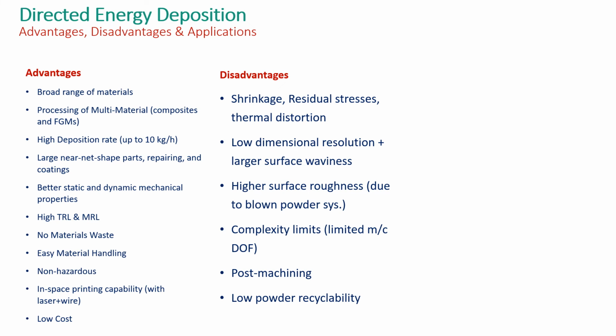If we had some rotational degree of freedom also, we could produce some more complex components. But because of the limited degree of freedom, we are restricted in complexity too. Post machining is also required because of the low resolution of the surface and low powder recyclability, because we are inputting too much energy. Because of that, the powder does not remain for the next use, and recycling is very difficult for this kind of application.